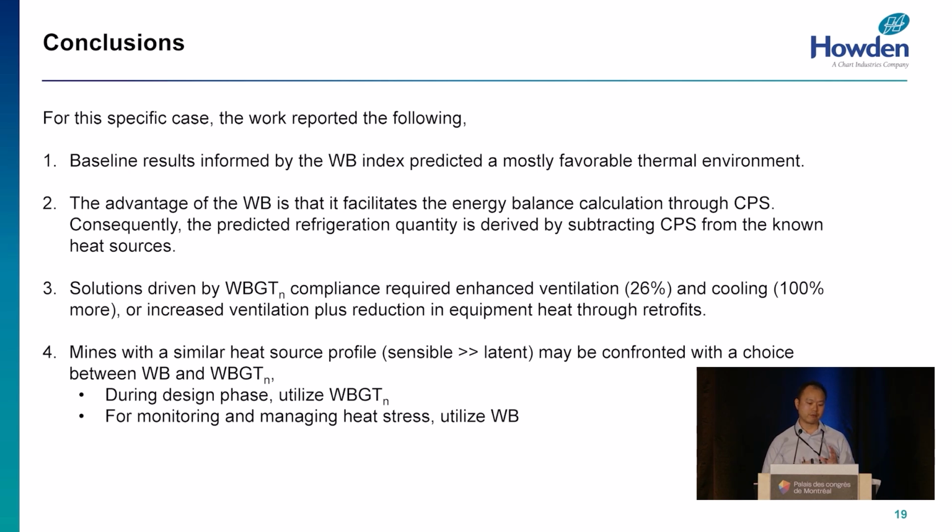My advice here is for the design phase, use the natural wet bulb globe temperature because it does offer a margin of safety. But let's say in this case, during shaft excavation, to expedite the work and for just monitoring levels of heat stress, go with the wet bulb temperature.